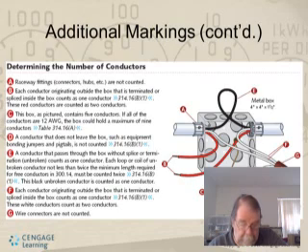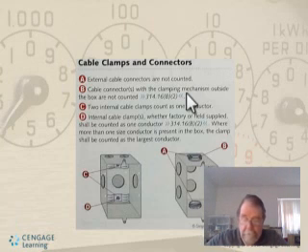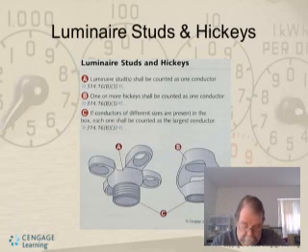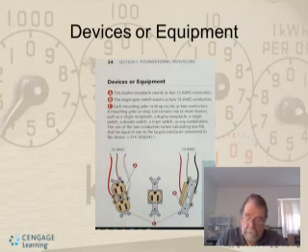And then here we got into the clamps again, which we've gone through already, but I figured I'd put that in there again. And we'll see the lighting fixtures, the holders for the fixtures, those count as one. And then here are your receptacles and switches. A regular receptacle with 2 outlets on it is going to count as one.